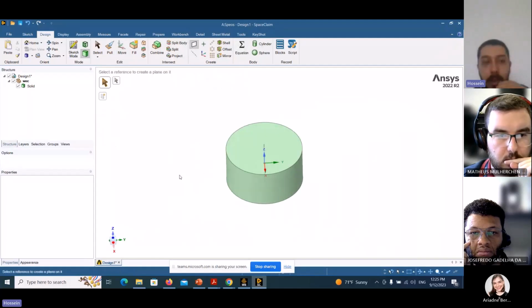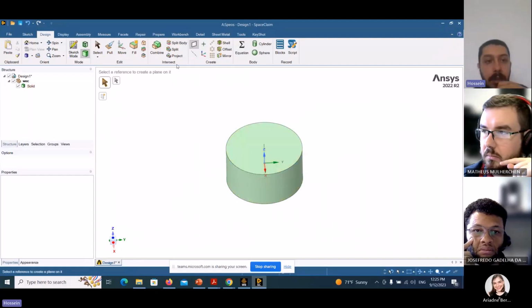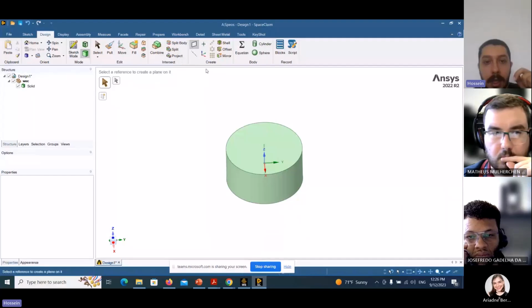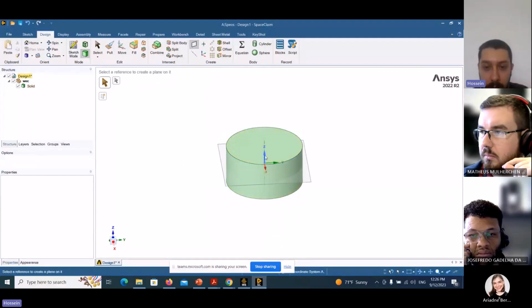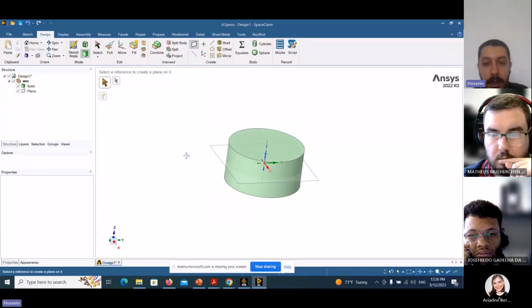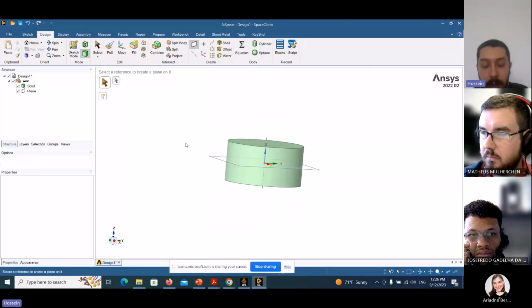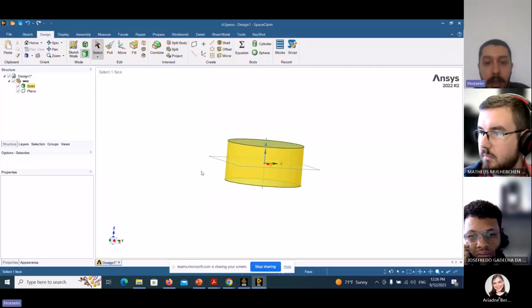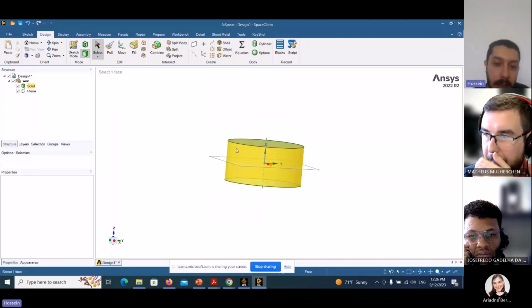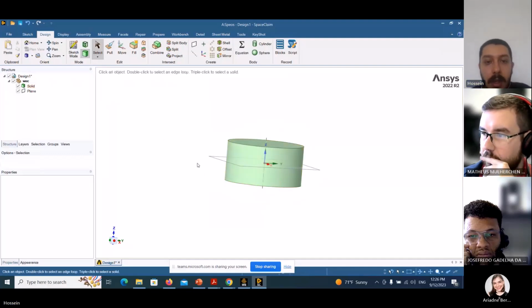First you have to put a surface. You can use this in the design parts and create a surface. You click on the z-axis, and the surface is put on the global surface on the surface waterline. And after that, you have to split these parts.